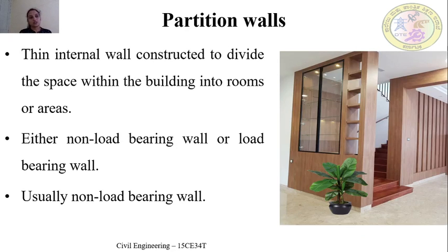Coming to the partition wall, they rest either on flooring concrete or on beams spanning between the main walls. Partition walls are generally carried either for the full height or for just above the eye level, at 2 to 2.5 meter above the floor level.